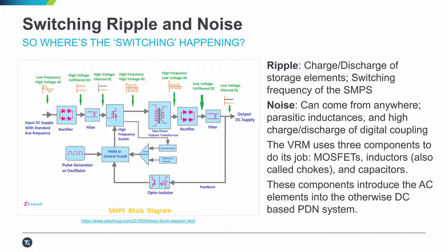And so to keep the operation of the power supply smooth and to reduce noise downstream, oftentimes developers will use things like capacitors and inductors. But of course, all of these components and the different sizes and shapes of these components, whether they're surface mount or through hole, they all perform differently over different frequency ranges. And so it's crucial to understand the variety of different components being used in the switch mode power supply and how they are changing over specific frequencies.